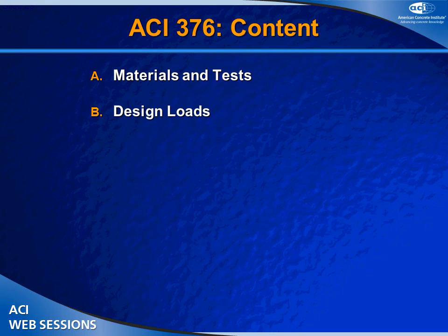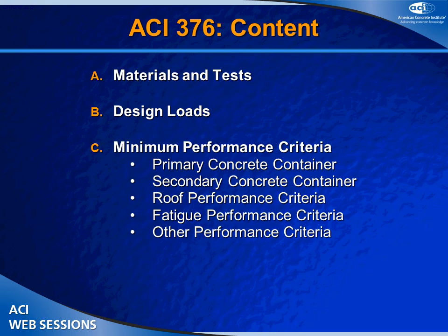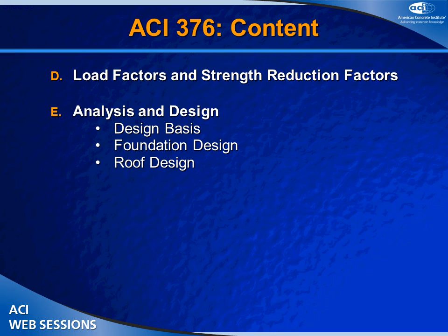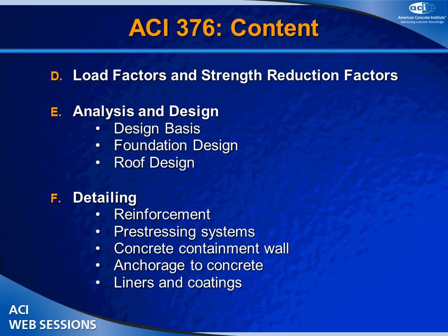Design loads. Remember it's design and construction. So we have some minimum performance criteria that we're putting into this that deals with the different containers, the primary and secondary containers, roof, fatigue, load factors, strength reduction factors. We always have to complicate the design for those kinds of things. Analysis and design: foundation, roof design, as well as the container design. So we're really dealing with the total project, the total tank, what it takes to get it in place. Detailing of reinforcing: the pre-stressing is a form of reinforcing, the concrete containment and anchorages, liners and coatings.